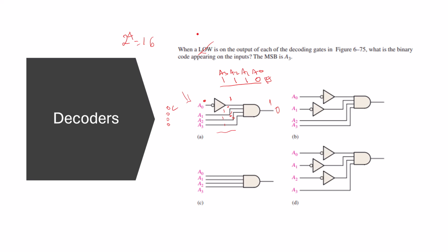So this gives us an answer to the question where we have the same statement, but instead of low, somebody says, talking about the high. Okay, what makes it high? Then our answer will be: make all the inputs 1 except the least significant, except A0, make it into a 0. I'm going to leave the rest as an exercise, but basically the same idea, no difference.